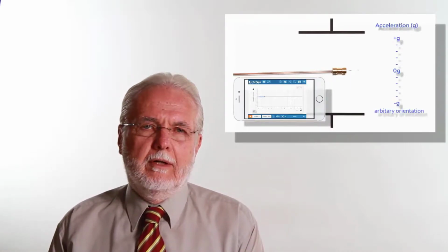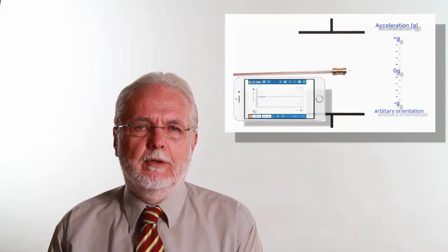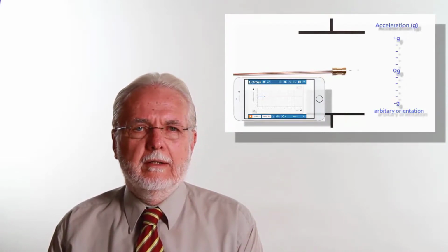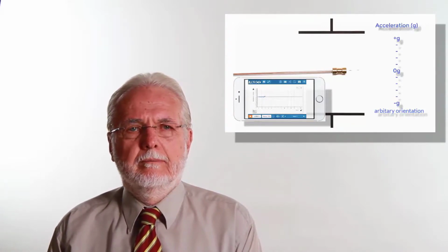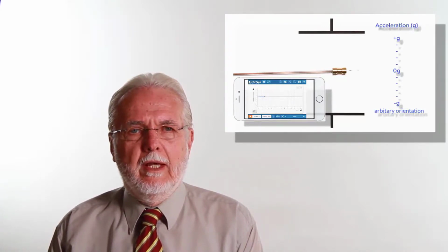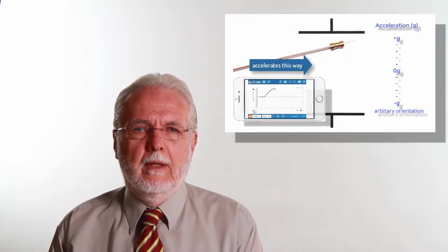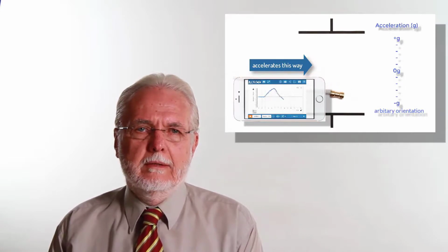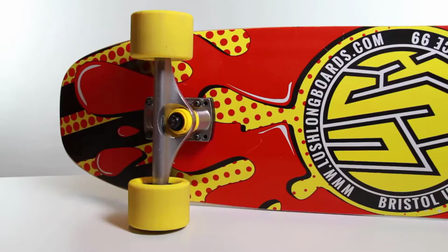The equivalence of gravity and acceleration are the second and third things Einstein might have checked with an iPhone. Laid flat, the iPhone will register 0g in the y direction. Acceleration in either the negative or positive y direction will cause registration on the screen. The inertia of the proof mass will bend the tiny spring within the accelerometer IC as a force is applied to it. This force will be the same for both gravity and acceleration.